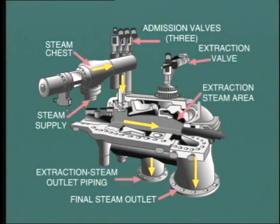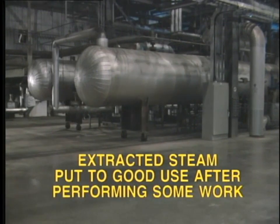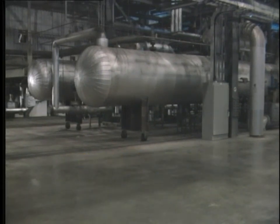At various stages along the steam path, steam is extracted from the turbine. This extraction steam is commonly used for feed water heating, but there may be other applications as well. The concept is that the extracted steam is put to good use after performing some work in the turbine. You will remember that we discussed this in the first tape in this series when we looked at efficiency.